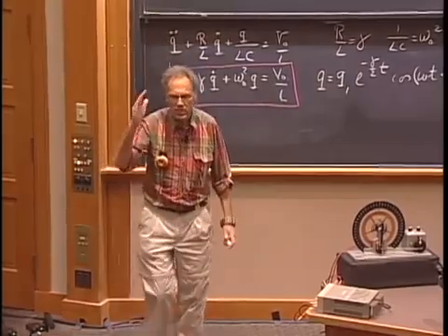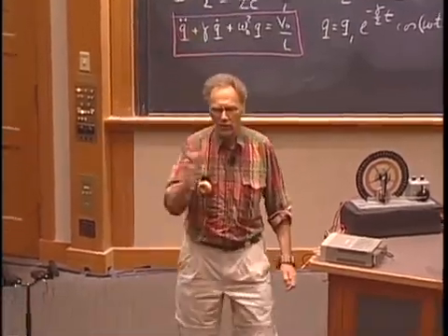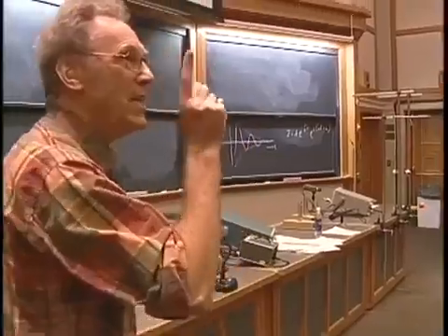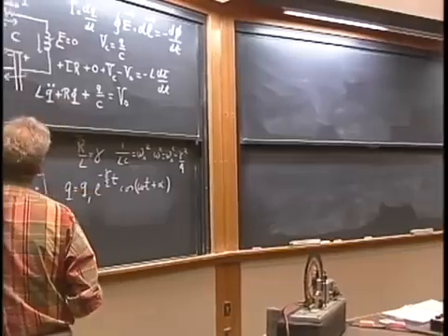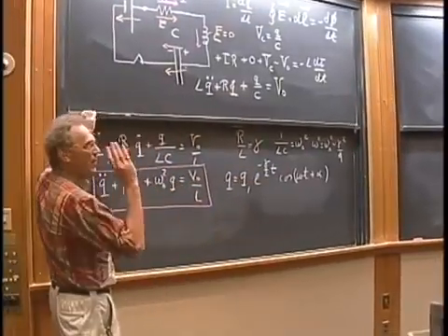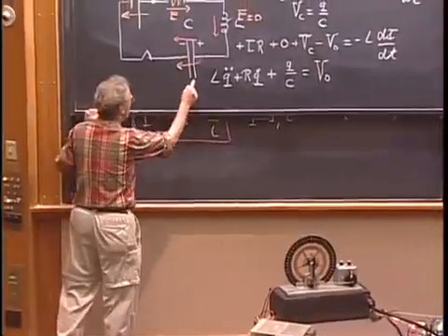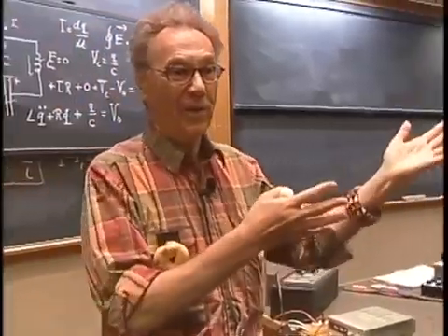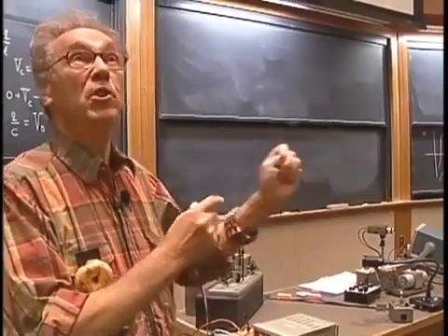In the case of the 0, it means that the oscillation would end up at x equals 0. Whereas here, the oscillation in the charge will end up, if we wait long enough, with a fully charged capacitor. Because when the oscillation has died out, the capacitor has been fully charged.